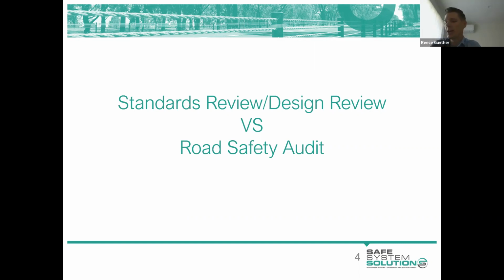When we're looking at intersections that we may consider to be unsafe, but meet the design requirements, we may think to signalize cross intersections in high-speed environments. We can design them to meet all the relevant standards, but when a crash does occur, typically it's a high-angle, high-impact energy crash, with poor safety outcomes, typically resulting in serious injury and fatalities. So just designing an intersection doesn't necessarily mean that it's safe.